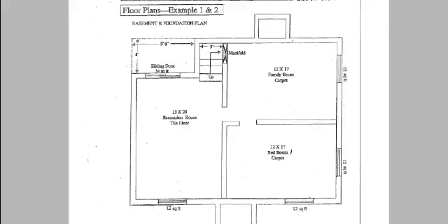So a few things that we need to notice that we're going to be using is, first of all, the dwelling location is in Surrey. So in this case we'll be looking up the design outdoor conditions for Surrey so that we can find out what our delta T is going to be. We also have a list of R values here for this particular portion of the structure. We show the walls are R14 and they're all above grade.